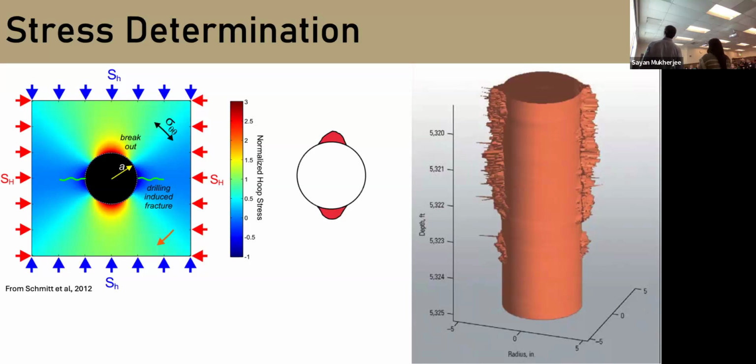And what this causes is these hemispherical regions of fracture and failure, dog-earing out at either side of the borehole. And we can see in 3 dimensions that the orientation of those breakout areas changes relative to the orientation of that largest horizontal stress.